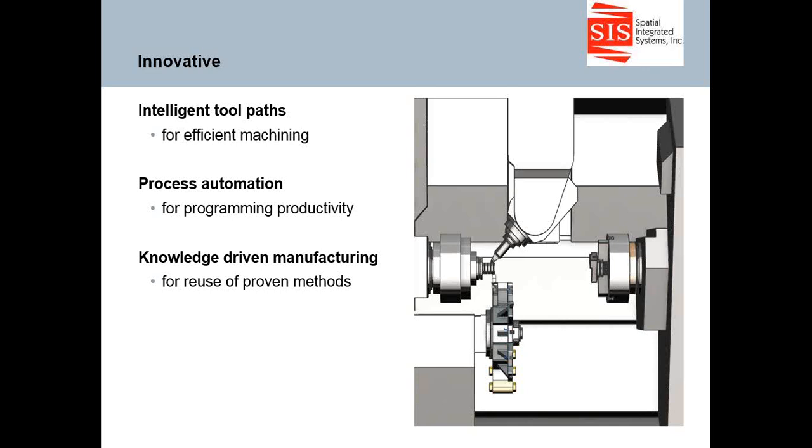With the feature-based machining in NX, you can automatically create optimized machine programs directly from the part design model. NX enables reuse of the proven method. You can manage and apply proven data to toolpath operations by using the machining database. NX automatically applies the right feeds and speeds for the given operation and tool selection.